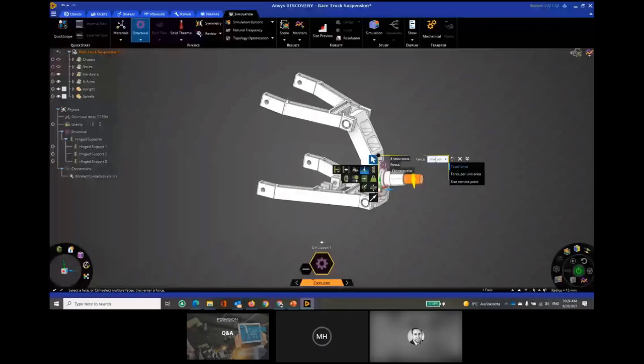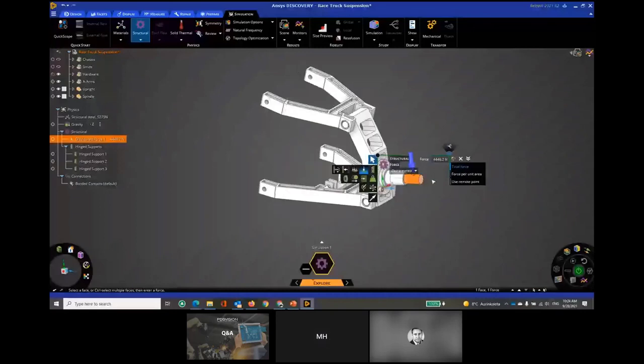If we are putting here, let's say, 1000, let's not put a Newton, let's put kips instead. So you'll get your force in here. We don't really care about the units, you can put in whatever units you want. Then this properties dialog here is something to look for. You at the moment have a direction of negative y. If you want to make this upwards, just put a positive in there.